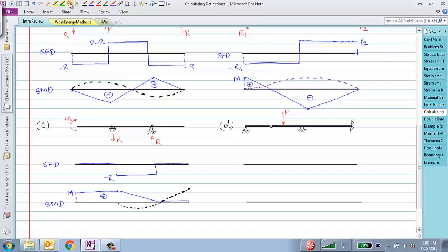And how about curvature in this half or this 1/3 of the beam? Curvature would indeed be constant because the bending moment is constant and curvature would be positive. So on the left side of that middle segment, we would have the beam curving upward. Sorry, there's not too much space out here. Otherwise, I'm just exaggerating the curvature here. That's why it looks like there might be a kink here, but of course there's no kink here, right? So this is the deflected shape for this part.